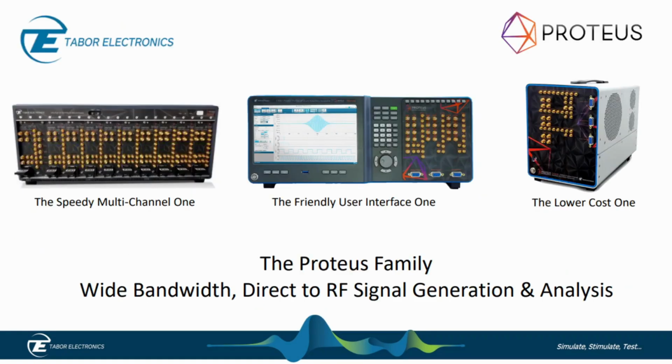As you can see here in the PXIe version, we can have many channels of operation. So if I'm designing an N by M MIMO system, I could have many channels, and I can control each channel's phase and amplitude or weight them in whichever way I want. I could stream that real time. I could make the adjustments, phase and amplitude or time and amplitude, very fine, or I could do it coarsely.